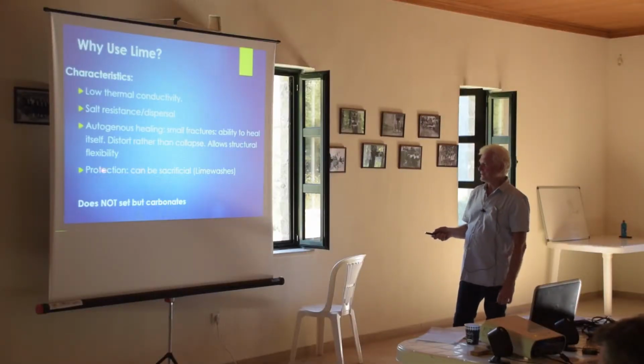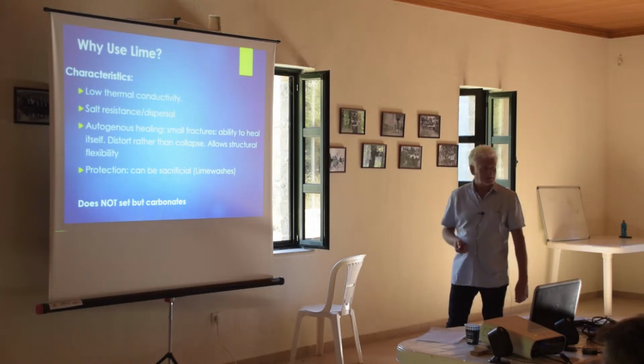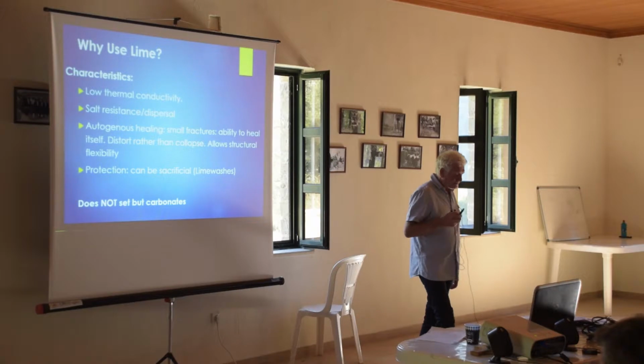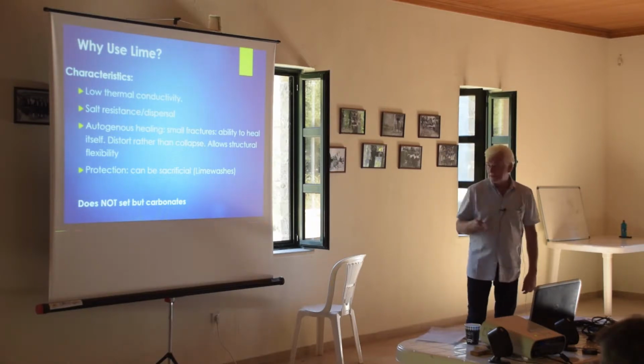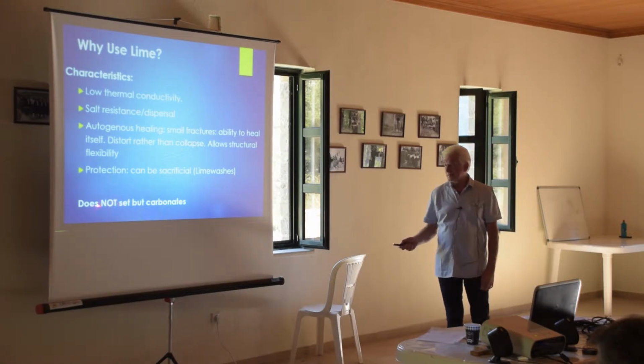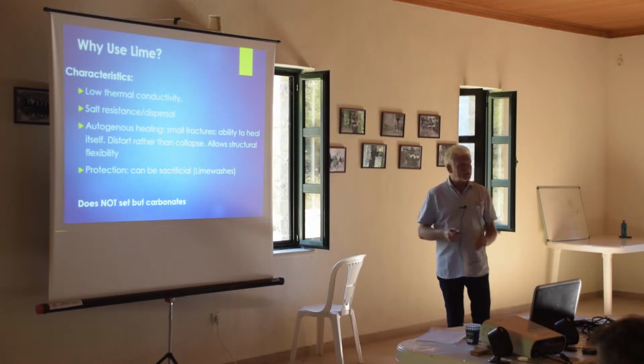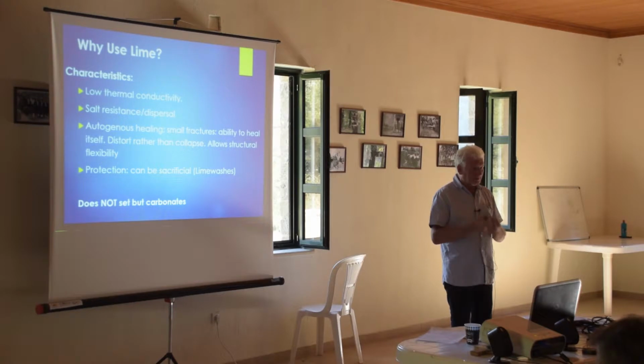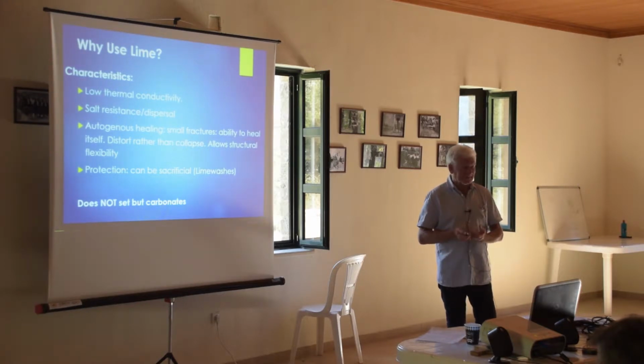It can serve as protection. It can be sacrificial, the lime washes, which we'll come to in the end. Now, the really important difference between lime and cement is that lime does not set. It doesn't become hard. It carbonates.